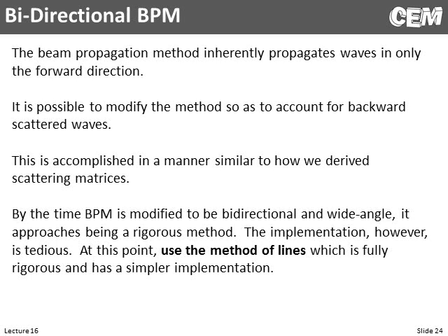Method of lines is a semi-analytical method. It's something we'll talk about later. So in my opinion, if you're using beam propagation method, it really should be for problems that it's well suited to. So one-way problems where we can ignore the backward reflected waves. Also problems where we can make the small angle approximation, where the fields are not changing very abruptly as they propagate forward.